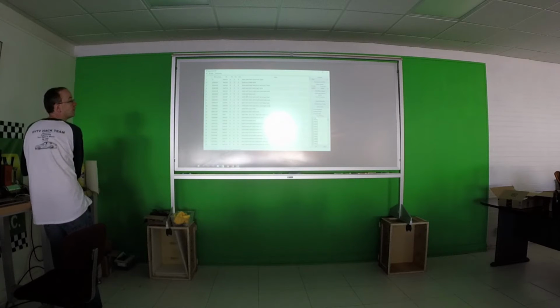So over here is filtering. This is every ID that was on the bus. And this was a capture that Jack took of using cruise control on the Tesla. So this is every ID on a Tesla drivetrain bus. But let's say that I'm not interested in all those things. I want to know about just ID 106. So if I say none here and select just 106, you can see that now I only have the 106 messages. That can kind of declutter a little bit.